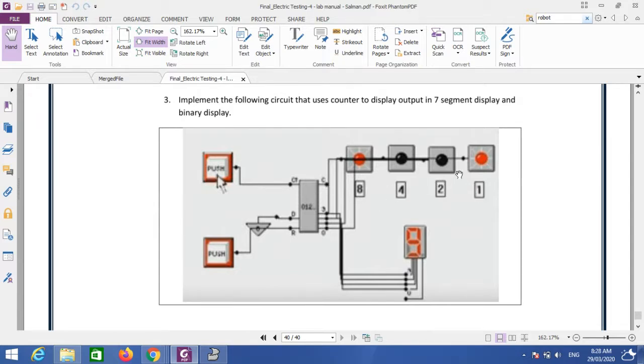Now why have I given this number 1248? Because as shown in the diagram, this is the number 9, in hexadecimal. This hexadecimal is converted into binary. The 7 segment LED gives you a hexadecimal value, and to represent a single hexadecimal digit, we need 4 bits.